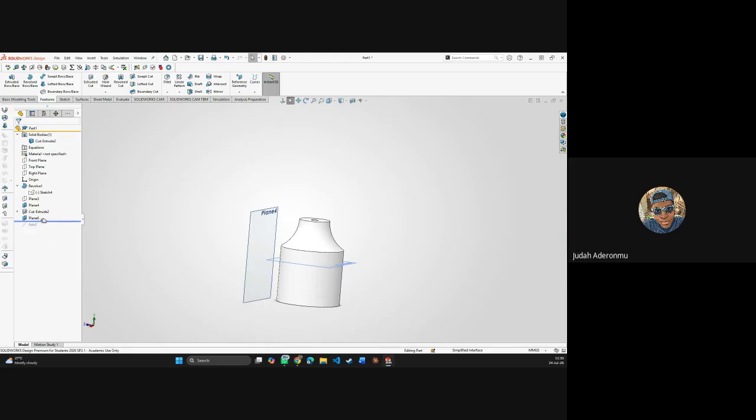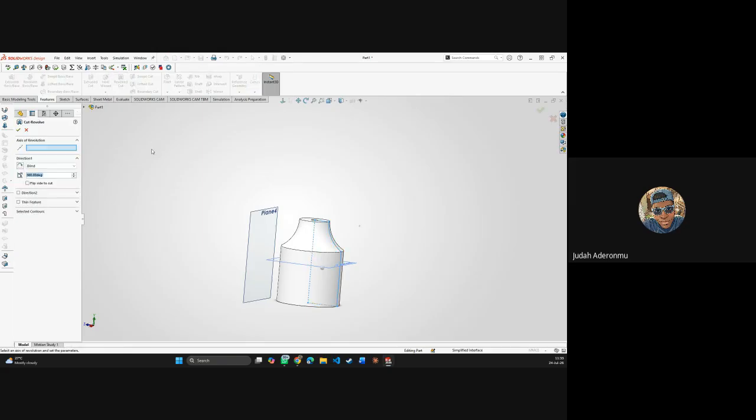let me just move my pen up. I'm going to click on revolve cut. Okay, I know what to do. I'll click here, click on revolve cut. I only cut this like 60 degrees.